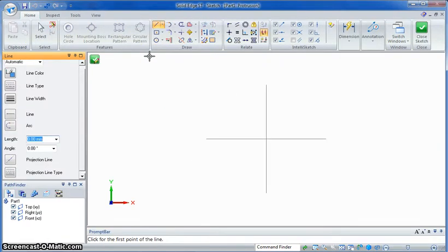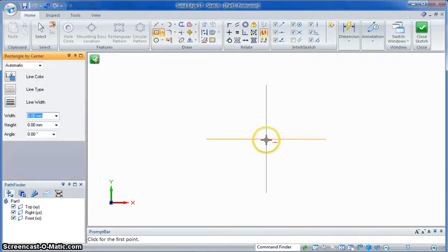I'm going to draw the base plate as I see it. I might draw it away from the reference planes. I find them quite difficult when it wants to snap to the reference planes and it's not the correct angle or length. So I'm going to move away from those. I'm going to make it 66 tall, and we have to add 44 plus 16 plus 16, which is 72. So I'm going to make it 72, tab, 66. Enter. And 0 angle.